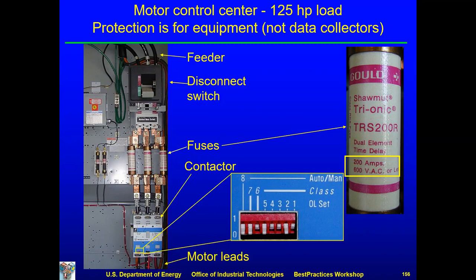You have to measure voltage and current, and then you take your voltage leads very carefully. If you were on the one on the left, then you touch the leads to the other two, and that measures the voltage. And then the power meter will give you the actual watts.